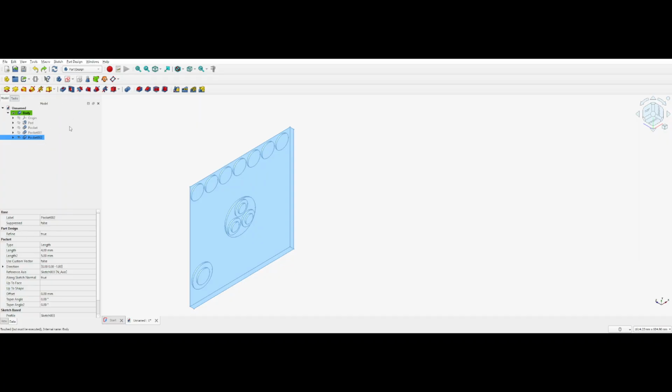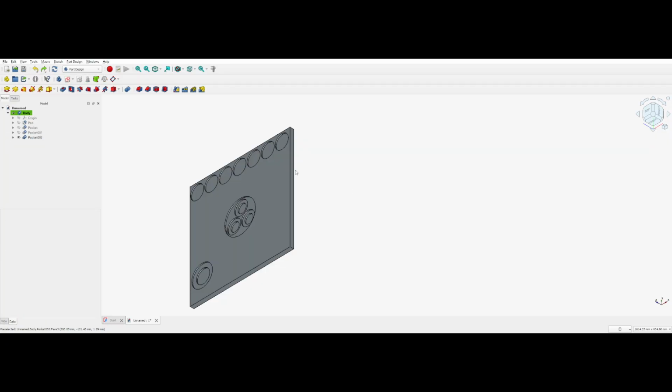And then you just want to save it as STL mesh. It'll show the extension .stl, and then you can bring the entire thing into something like Orca Slicer, or whatever slicer you use, and subdivide it there, so that you know exactly what sizes and dimensions you have on your print plate. And that should be the entire tutorial.